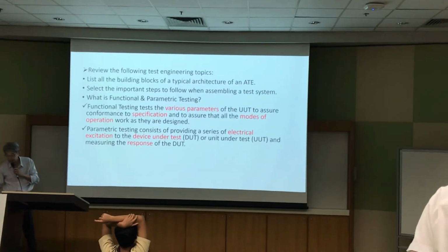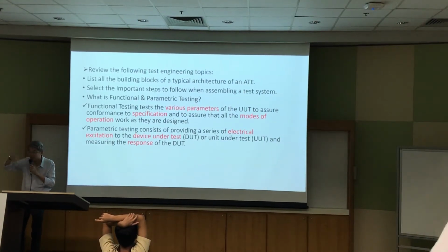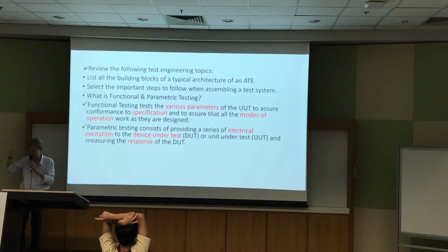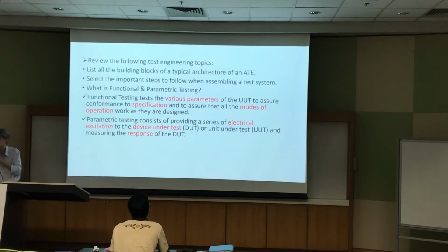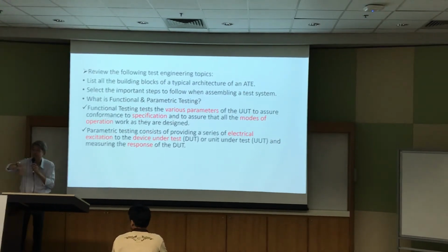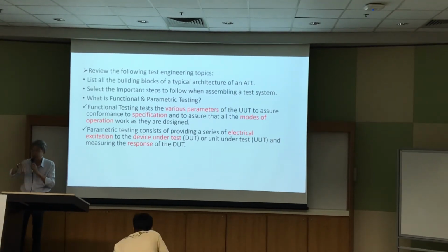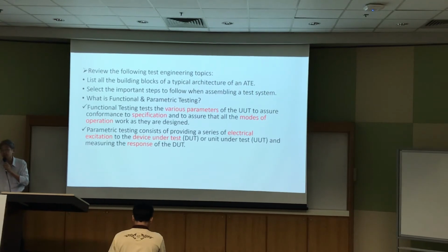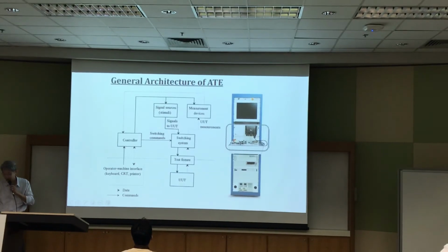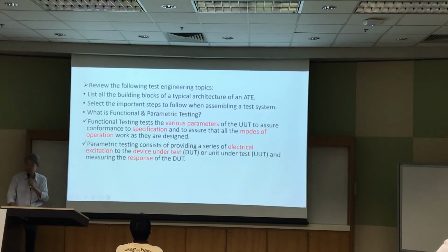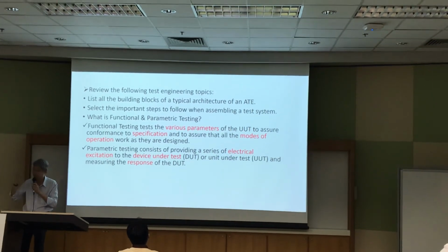Whereas parametric testing is testing the individual components as you assemble your parts. Let's say you put an IC there, and the IC is pretty expensive. Better test it after putting it. Because before you put in, it was working. But after you put it in, soldering process, what else you need to put it in, it may not work after that. So you better test it first before you put further more components. So those parametric testings are all done intermittently along the production line. And then finally it comes to the final testing, which tests the entire product. So there's a difference between these 2 tests. So once you got that understanding, you are fine.